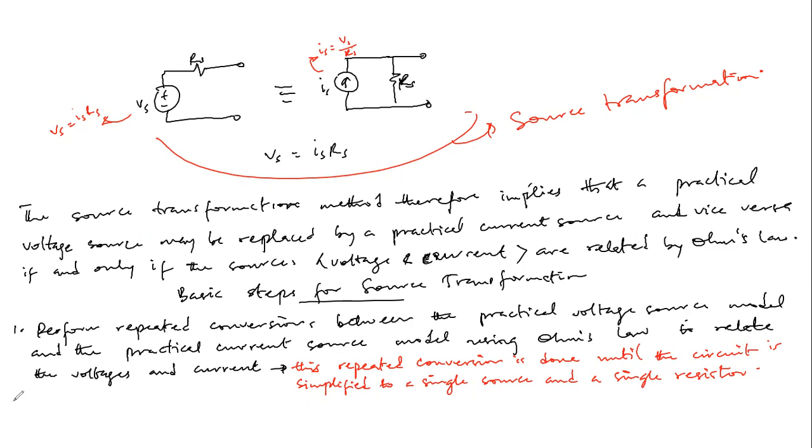And then the next point to take note of is using Kirchhoff's voltage law, the KVL, you add series voltage sources. Don't forget that the voltage applied across nodes is the same. So all elements connected in parallel having a common node have the same voltage applied across their terminals.